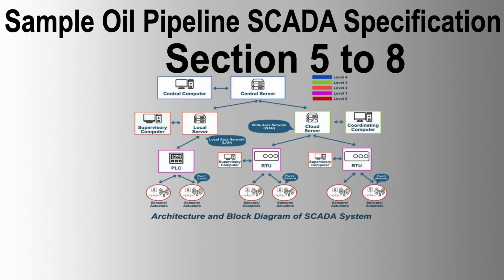5.7 Enclosures. RTUs and associated hardware shall be mounted inside suitable enclosures accommodating full future expansion. Enclosures constructed from marine-grade aluminum, insect, weather, and vermin-proof, conforming to IEC 529-1 IP55 standards. Enclosures for outdoor installations shall have sunshades and document pockets for storage of documentation.